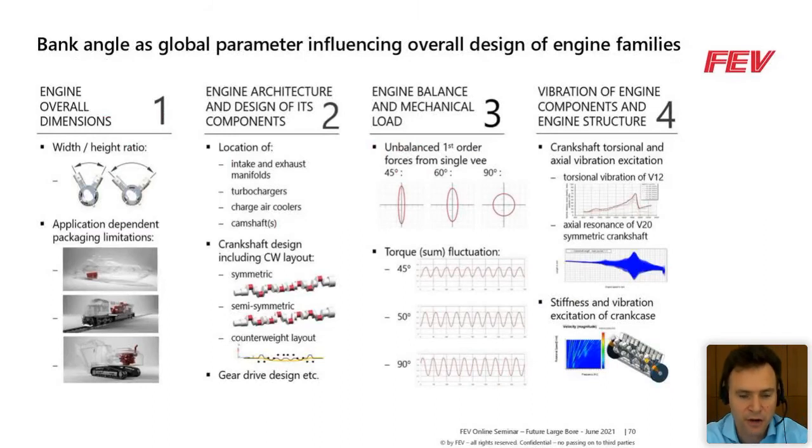Of course, the V angle is not driving all the turbocharger position, but it's clear that the V angle is also very important for many other parameters like torsional vibration, like for engine mechanics in general, like, for example, the crankshaft layout with different layouts for symmetric, semi-symmetric, or counterweights. So at the end, we have developed a quite holistic approach to define the V angle, where we start